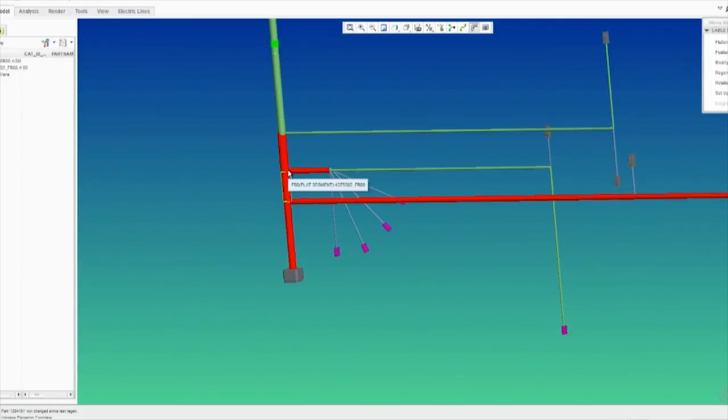But then I'll break dependencies to that cab by redefining my location points to an offset coordinate system, so that I don't keep those parent-child relationships as I finish up my design. I may keep those references in my initial design, as fluid as things change sometimes early in an NPI cycle, but I always break them before release. And if you don't know, Caterpillar uses Teamcenter, not Windchill, to hold all our data. Windchill's a little bit more finicky about how it keeps those references, and I don't want to have to pull down an entire machine just to open a harness.